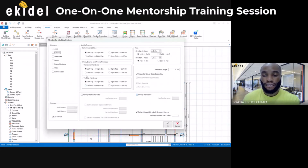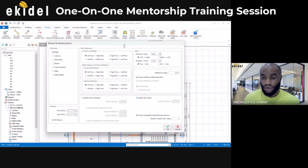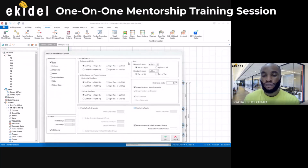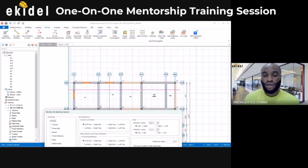This will not display. I want to rename just the axis. So I'll come here and check this axis here. And then I'll come here and it says axis direction, direction 2 and direction 1. Direction 1 is telling you the axis going in the X direction like this, the one that is going horizontal.